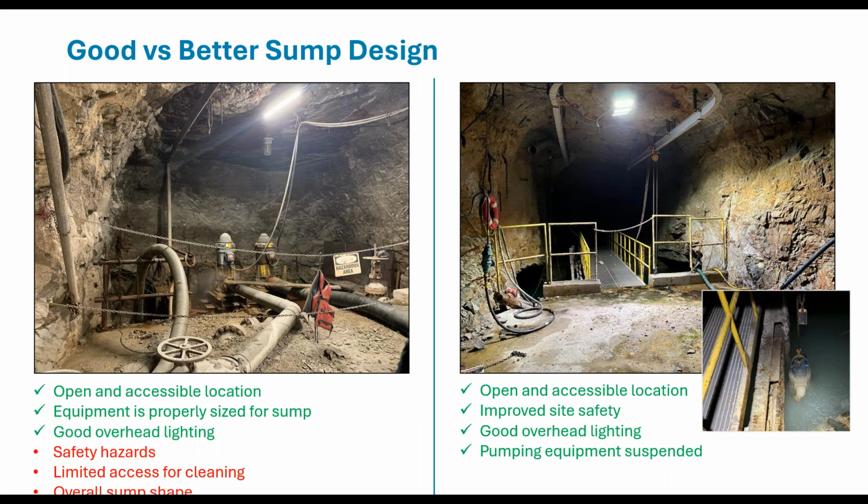It also appears that there's some water spraying from the pump on the left, likely relating to the need for changing the seal packing. And you need to understand how difficult working on these pumps would be for your own personnel or for a service provider coming on site. Safety is always our first concern, right? People are our most important resources. So giving them an environment that is as safe as possible in which to conduct their important work is very, very important to us. Now, switching our focus to the sump on the right.